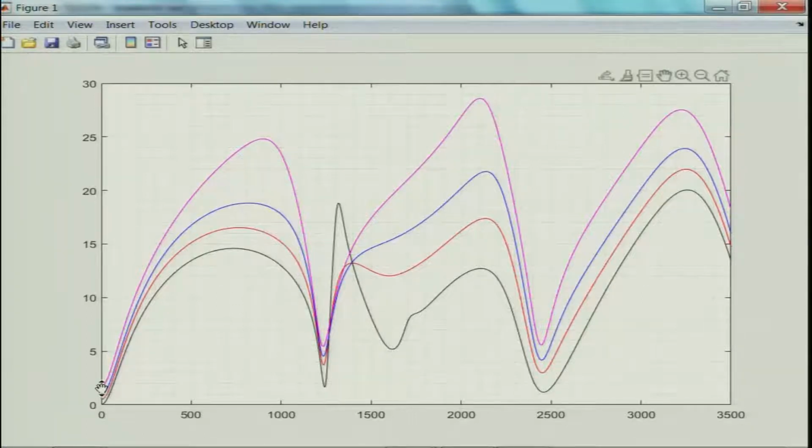Transmission loss always starts from 0. The fact that it is still at 5 hertz frequency, it is still about 1.84. Elnadi's expression, the modern expressions tend to slightly overpredict the transmission loss even at very low frequencies, but of course we need to do a more thorough, maybe experimental, corroboration of all these things. But nevertheless, one thing is clear using the modern expressions where mean flow and mean bias flow and mean grazing flow occur simultaneously, and these expressions can readily take care of that. We will also use the previous expressions known before and see how the shape of the curve changes.